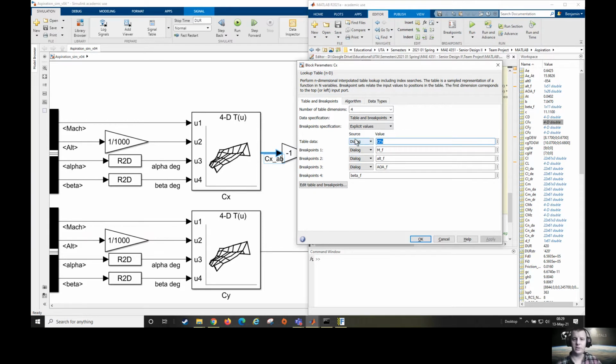the easiest way to do this is VSP Aero. I'll provide a link to it. It's also free, open source. And you would basically just do a sweep of alpha, beta, Mach number, in this case, altitude, if you wanted to set it up exactly the same here.